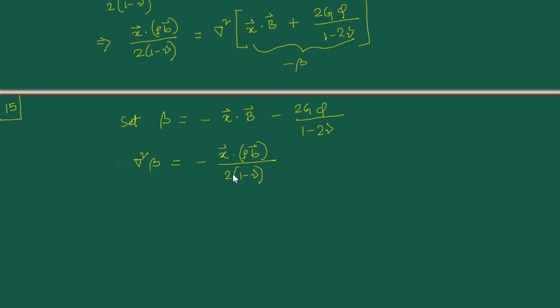So is it not true that this here again is a Poisson equation where we intend to solve for beta? Previously we had arrived at a Poisson equation involving the vector b. Now we are arriving at another Poisson equation involving the scalar beta. So we box this equation. This will be another part of the Papkovich-Neuber representation.